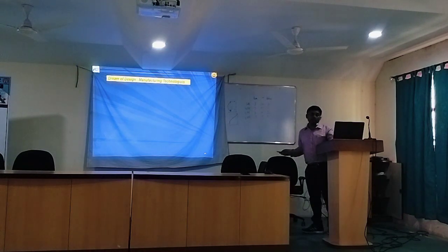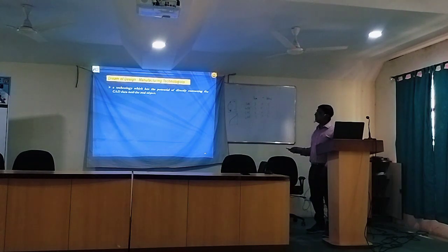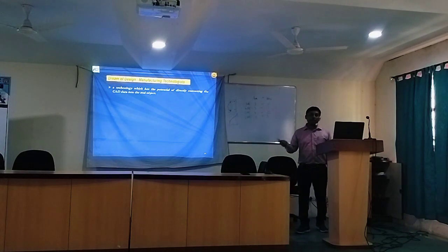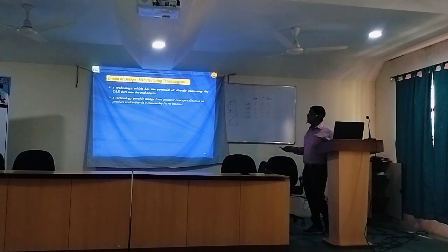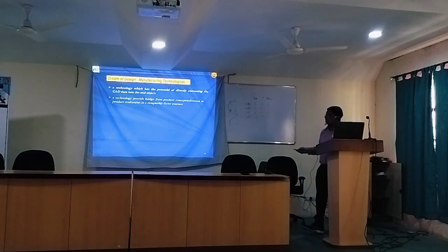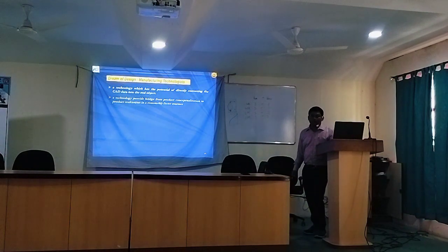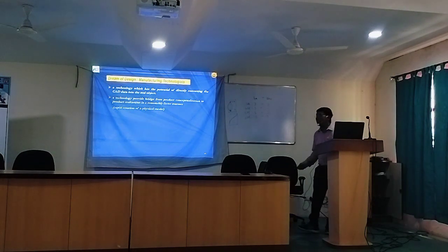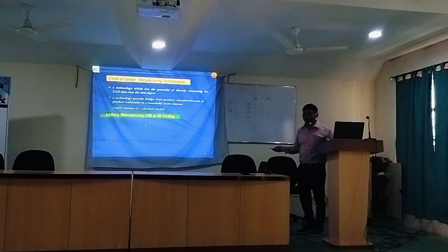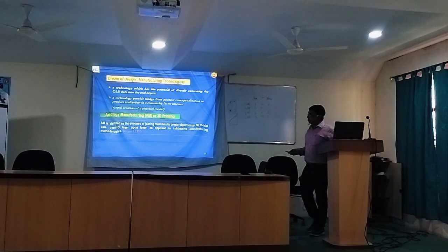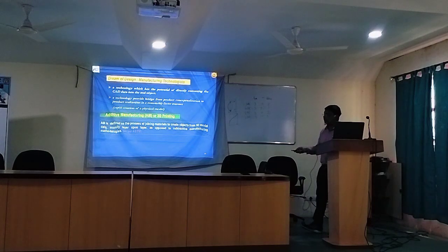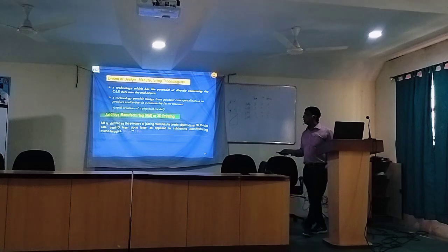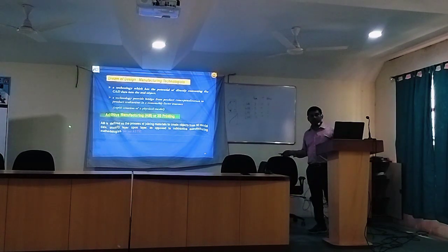Once upon a time, it was a dream for manufacturing technologists to develop a technology with the potential of directly converting CAD data into a real object. That means the technology provides a bridge from product conceptualization to product realization in a reasonably faster manner, that is, rapid creation of the physical model. Now it is a reality in the name of additive manufacturing. Additive manufacturing is a process of joining materials to create an object from 3D CAD model data, usually depositing material layer upon layer. It is opposite to the subtractive manufacturing methodology, and this definition is proposed by the American Society for Testing and Materials.